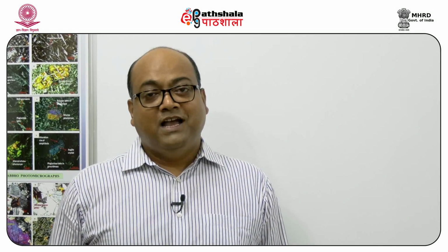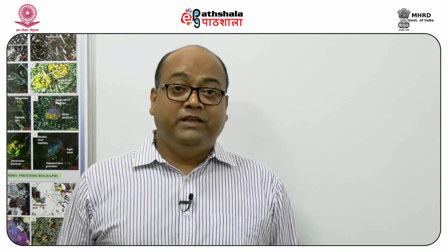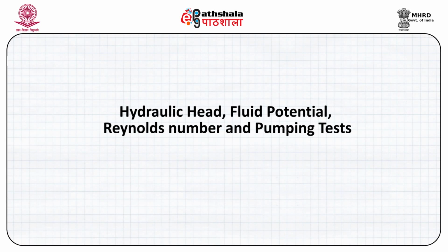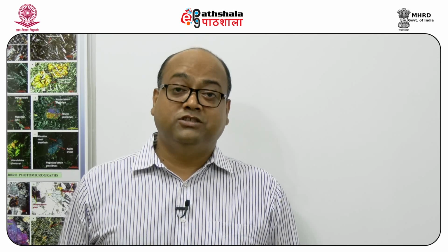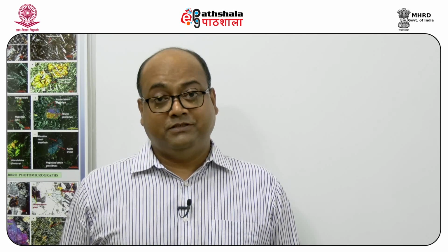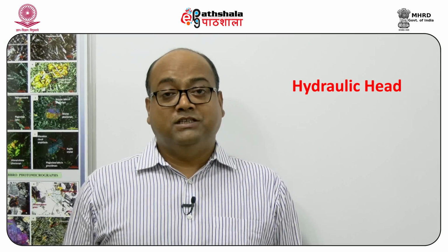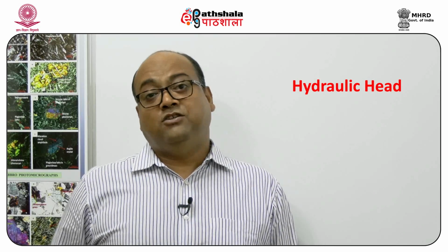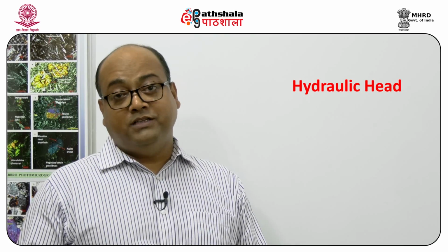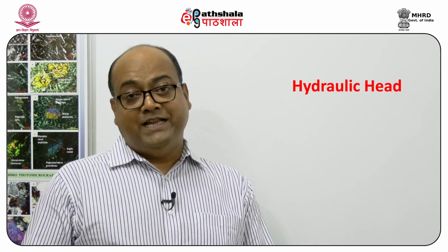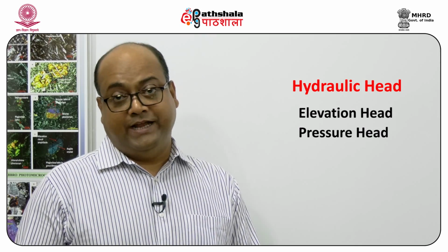In this module, I am going to talk about how we measure hydraulic head in the field and how the measurements of hydraulic head and the differences in hydraulic head are used to measure important hydraulic and hydrologic properties of different aquifers. So in continuation, I would first like to say that hydraulic head is basically the sum of two components. One is the elevation head and another is the pressure head.